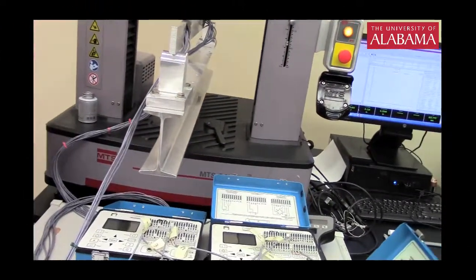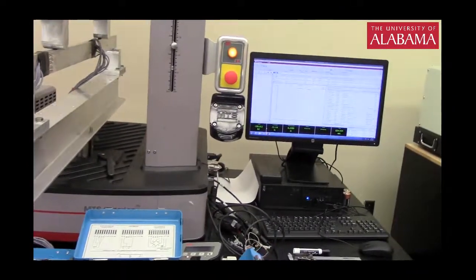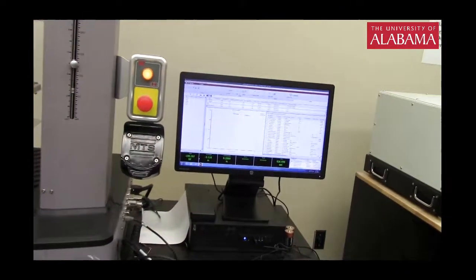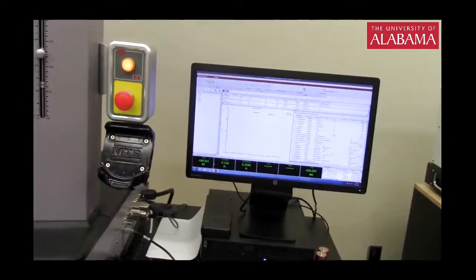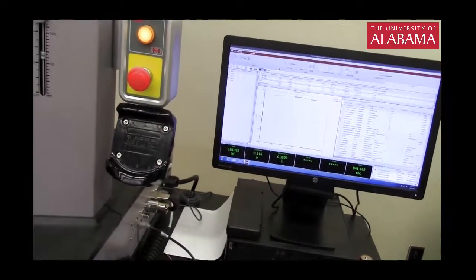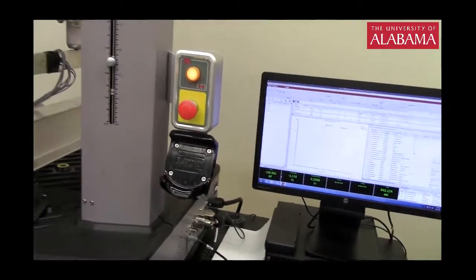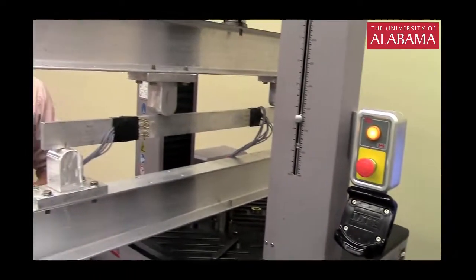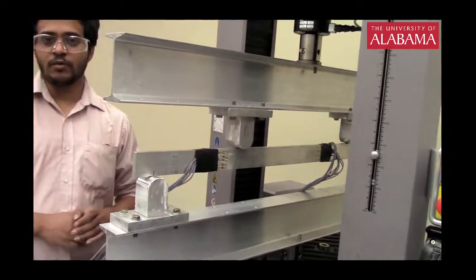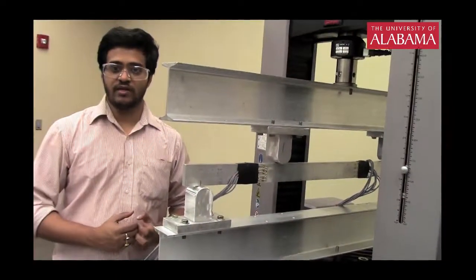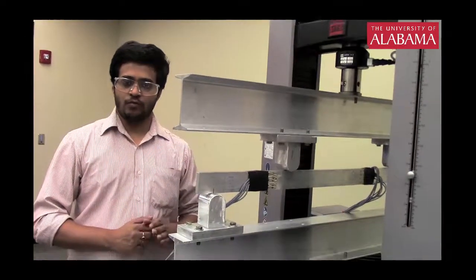So continue this. Increase the load to 400, 600, then 800, then 1000, like it is laid out in your manual, and record the strain gauges, and then come back to 0 again gently, and record the strain gauges again at 0, because you want to get the 0 reading before and after the experiment, because that will help me to grossly estimate the error.